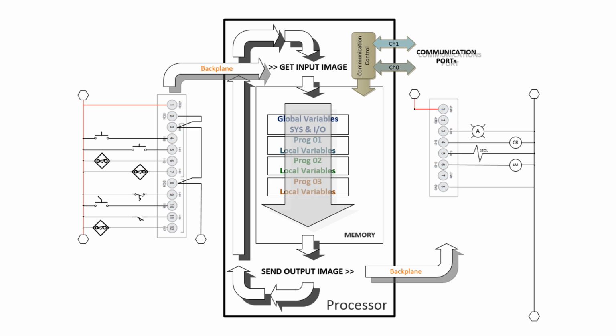In this case there is no real backplane because the Micro800s, especially the 810, you cannot expand. Now the 820, 830, 850, and 870, you can expand the I/O. So theoretically it does have a backplane even though it's encapsulated in the plastic box, and you can see where the modules insert on the front.